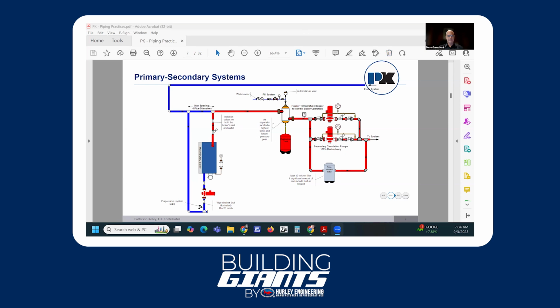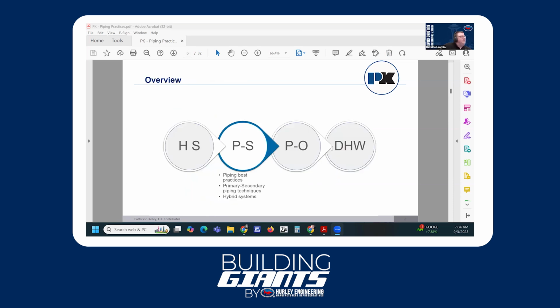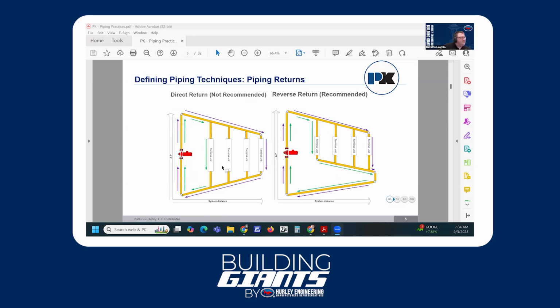Okay, good deal. So I'm going to back up for one second because I think yesterday we kind of left off after talking about the basic system piping arrangements. I wanted to go back and make sure we had talked about direct return versus reverse return. The drawing on the left here is a direct return system. So basically, as the fluid goes out, we go through each terminal or heat emitter in our system. Again, this could be a chilled water system as well, not just a heating system. And then we come back.